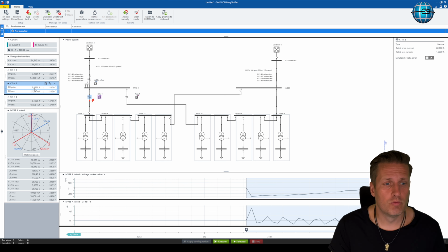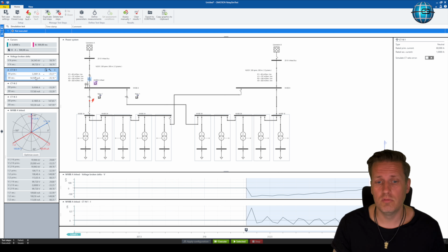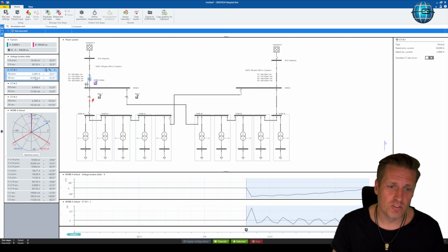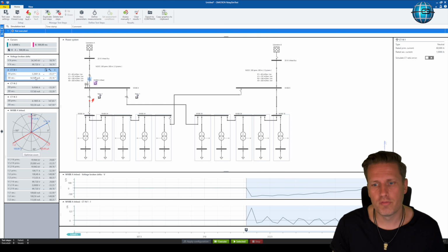grid. And if you want to determine the smallest value for your relay setting in order to make sure that you have a proper starting amount, you can just take this amount here, or you can even look if you find another combination with the smallest capacity available, and then you can say I take the half of this value, and then you have a perfect starting value for your ground fault measurements.